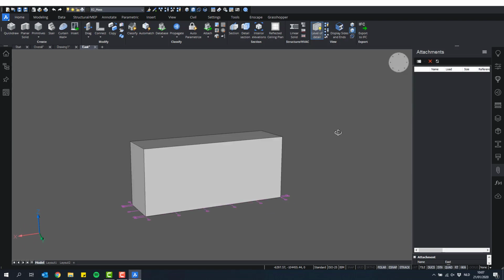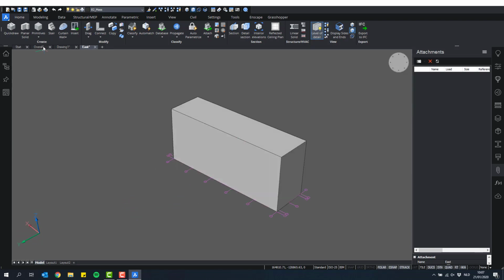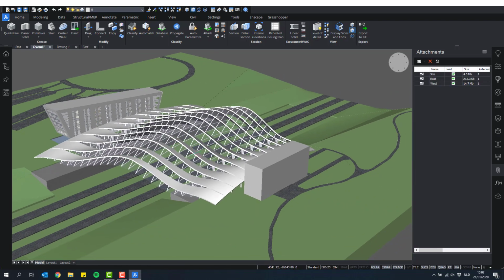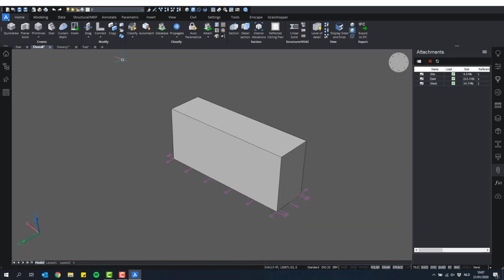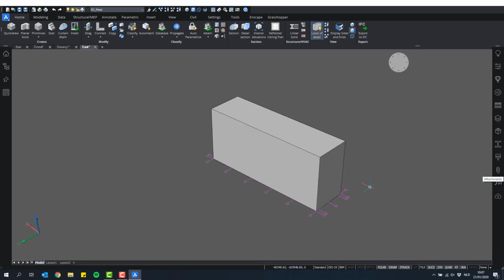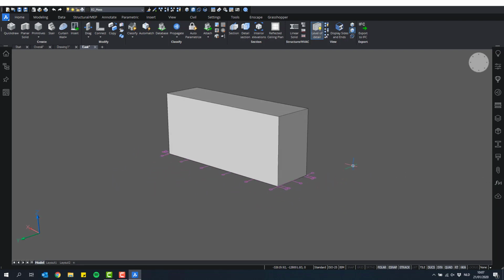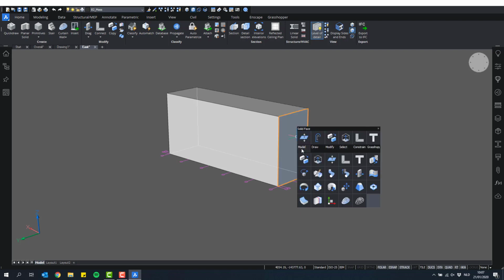Now we will sculpt this box into a building. Actually, we want to create a building that's quite similar to the other one here, to this west building. It's going to be a similar shape, so we'll do this using direct modeling. The first thing I'm going to do is rotate some of these faces. So as I said earlier, when I'm modeling, I usually have my face detection on, so I will leave it like this. I want to rotate this face around this axis. So I'm going to highlight this face, and in the quad under the Model tab, there's this Rotate tool.